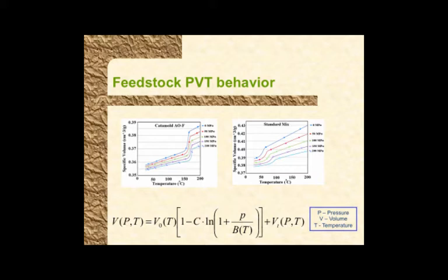For a given pressure, as the temperature reduces, the volume is going to change. If the volume changes, what happens? The part is going to shrink. So if the part shrinks more than it's supposed to, your dimensions are going to be off compared to what you want to predict. So that means in the process, you have to raise the pressure and add more material to compensate for the volume change. So this set of properties, and this is called a Tate equation, just says how does volume change as a function of pressure and temperature.